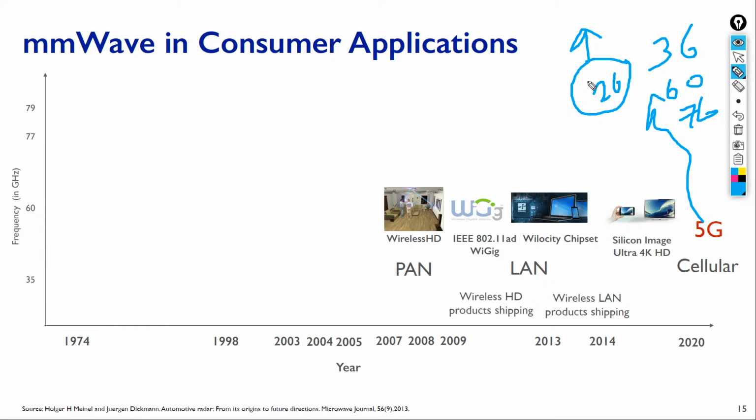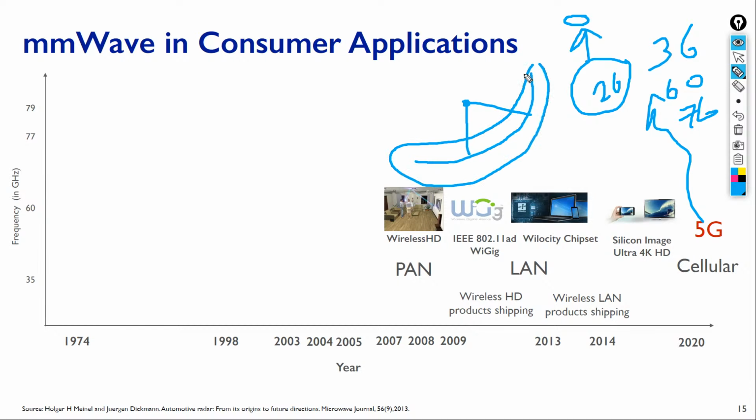So it's kind of backhaul. A human being can never usually come on top of the dish and put his hand on it or block it. And usually when you install the dish, you bring a technician to install it for you, and you see how careful he is while aligning the antennas. Let's say this is the dish. Since you are using 26 gigahertz for TV, the antenna is basically this tiny thing here, because 26 gigahertz is a very high frequency, meaning very low lambda. Lambda is very short, and the dish is just to reflect, gather, and concentrate energy to the antenna, so that the antenna has enough energy to decode the signal, increasing the signal to noise ratio.